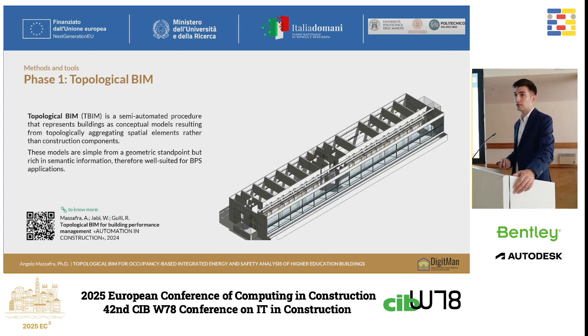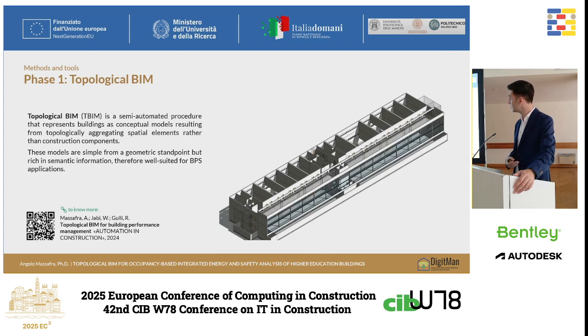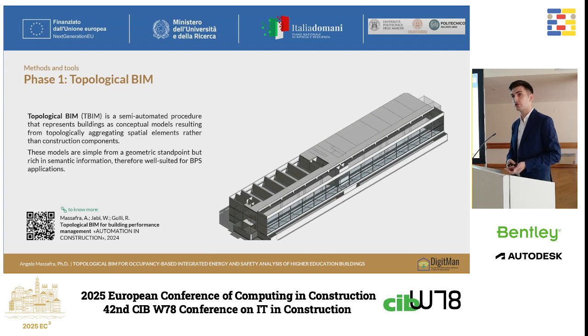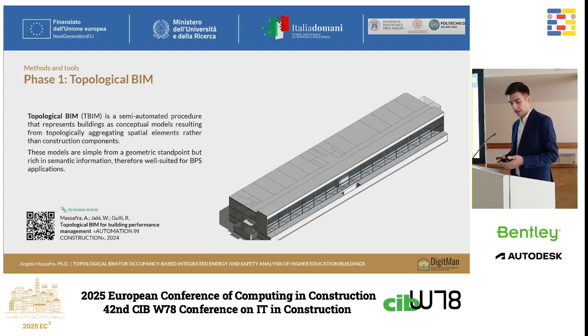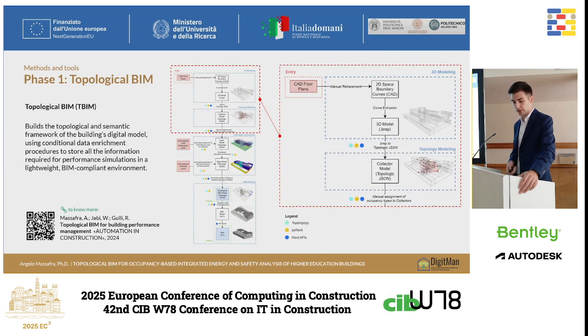It's basically a semi-automated procedure to make building information models in a standardized and semi-automated way, modeling the building by spaces rather than components, and generating models that are simple from the geometric point of view, but are rich in all of the information that is needed for carrying out many kinds of simulation. And for this reason, they are well suited to BPS applications.